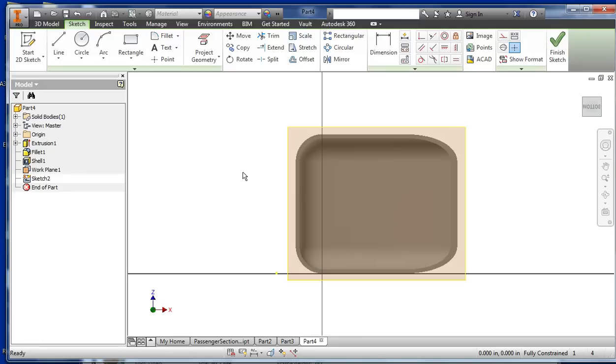So I'm going to begin by drawing a rectangle. I don't want to have any constraints. So just click once, pull it away, try to make sure there aren't any constraints that were automatically being applied where the corners are already stuck next to something or on something. And now let's get our dimensions of this rectangle.